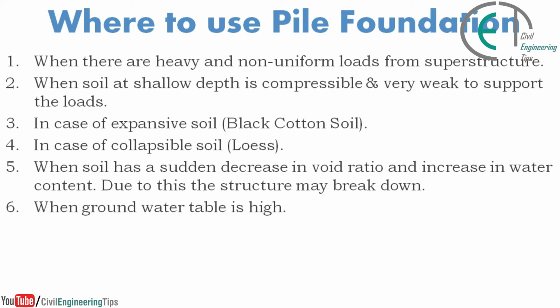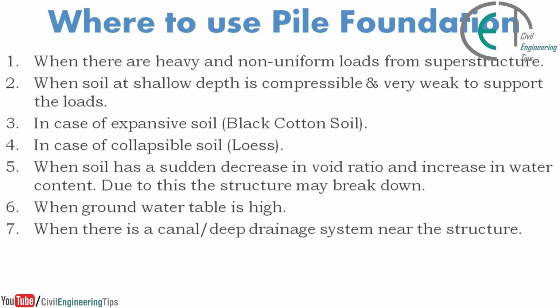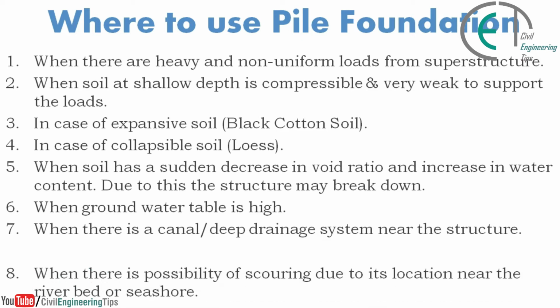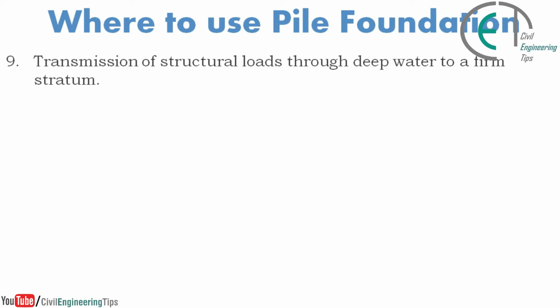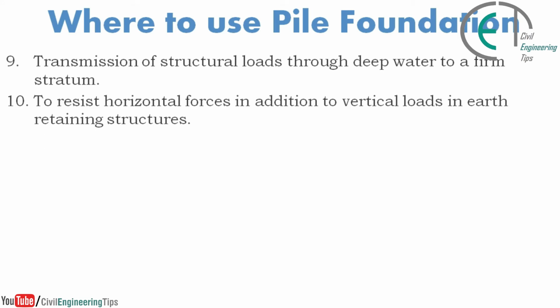When groundwater table is high. When there is a canal or deep drainage system near the structure. When there is possibility of scouring due to its location near the riverbed or seashore. Transmission of structural loads through deep water to a firm stratum, to resist horizontal forces in addition to vertical loads in earth retaining structures.